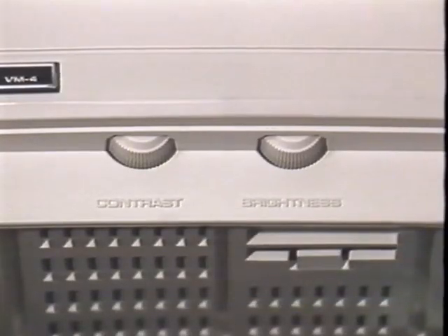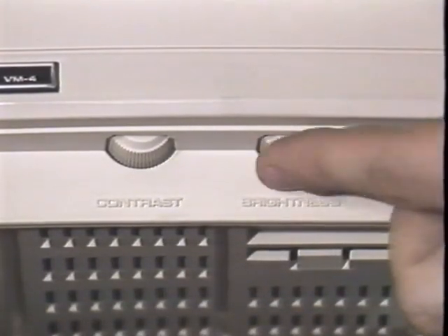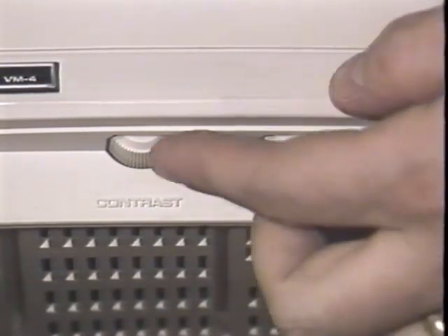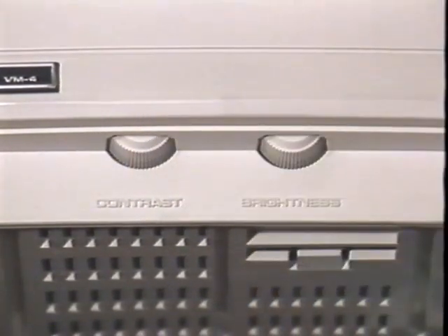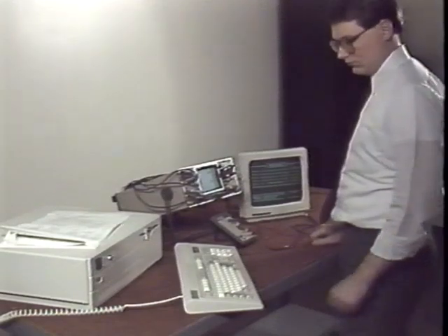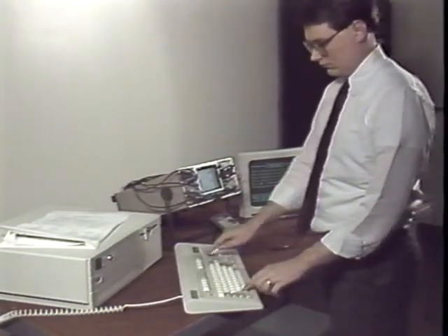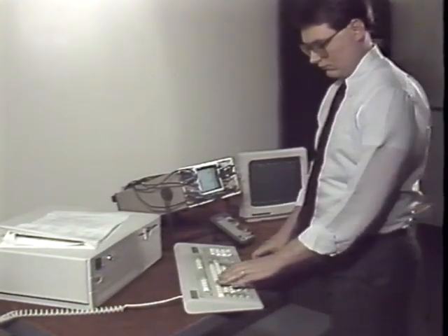Once brightness is set, move on to the focus adjustment. Set the external contrast and brightness to maximum, since focus is poorest when the screen is bright. Select a diagnostic option that places characters on the screen and adjust the focus control until the dots and lines of the characters are as sharp and as small as possible, both at the center and in the corners of the screen. Once the focus is correct, we have completed all of the electronic adjustments of a monochrome monitor.